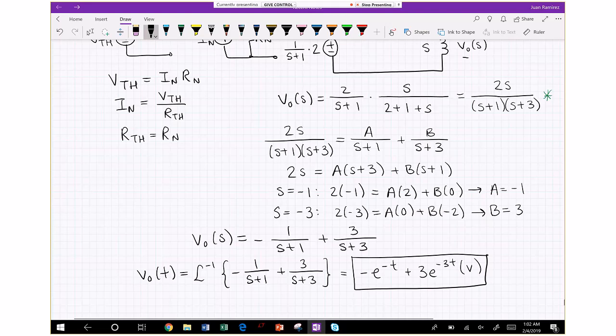So then what we do is we convert each component to the S-domain. We model it with the S-domain model for resistors, inductors, and capacitors, and that is an impedance. And then for voltage and current sources, we simply take that signal that's being used as the input and convert it into the S-domain with a Laplace transform.